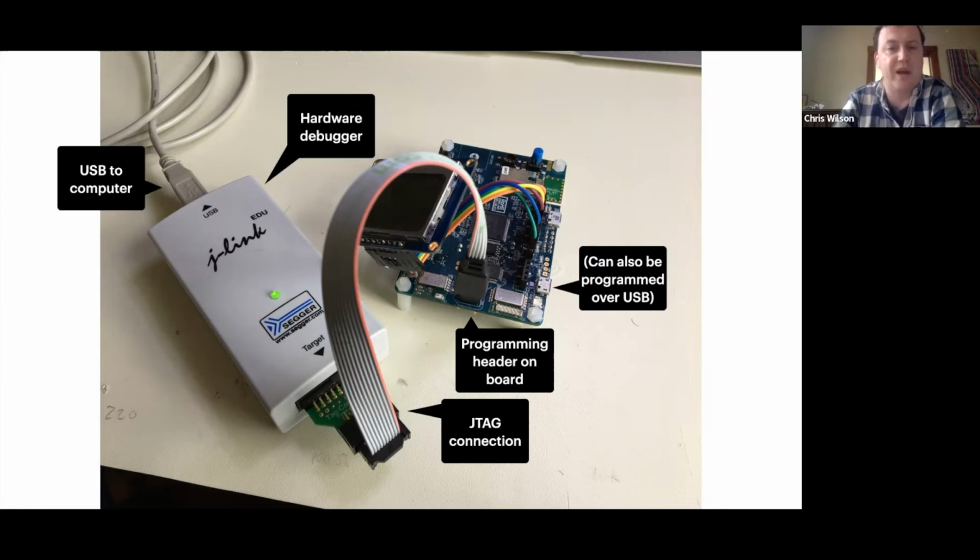So besides just putting your code on the device, you can also debug the code while it runs on the device. On your desktop, you connect to a GDB server that behind the scenes is talking over this JTAG link directly to the board. And you can do things like pause the execution and step through memory and do all sorts of stuff.